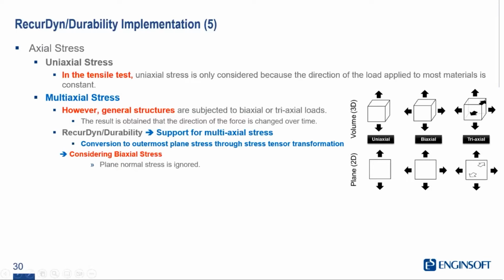The next approximation is a biaxial stress, where you've got two primary directions, and then triaxial you've got three. In reality, when we're looking at the surface of an object, we can discount the triaxial stresses. So we're basically always choosing between assuming a uniaxial stress and assuming a biaxial stress.